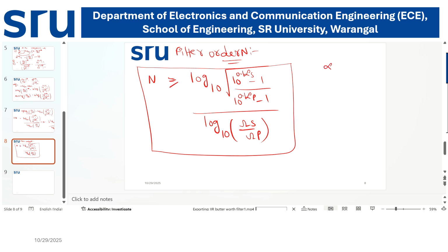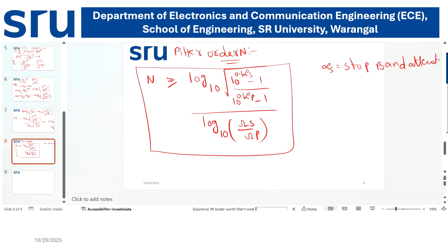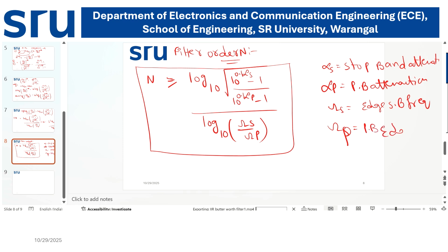Where alpha s is nothing but the stop band attenuation, and alpha p is nothing but the pass band attenuation, and omega s is the stop band edge frequency and omega p is the pass band edge frequency. So from the characteristics, if we know these four values, then we can easily determine the order of the filter.